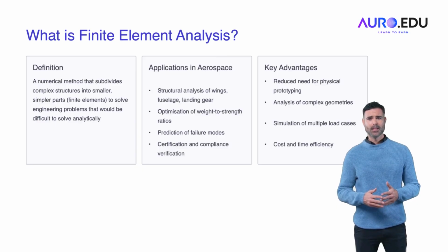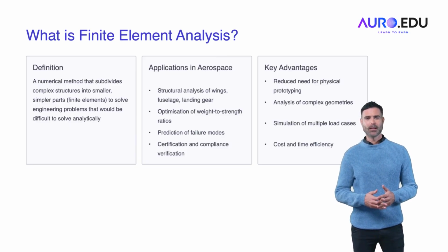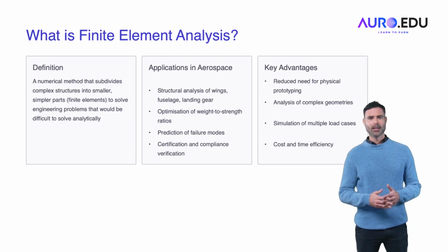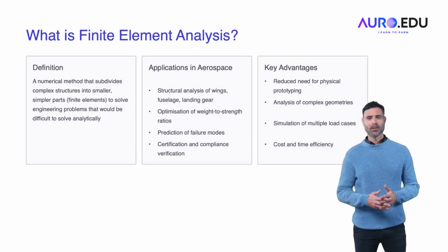The method is essential for optimizing weight-to-strength ratios, ensuring that aircraft structures are as strong as necessary without being unnecessarily heavy. By simulating the behavior of the structure, engineers can predict failure modes, identify weak points, and optimize designs to meet stringent safety and performance requirements. The primary advantage of FEA is its ability to simulate complex geometries and load conditions that are difficult or impossible to analyze analytically.